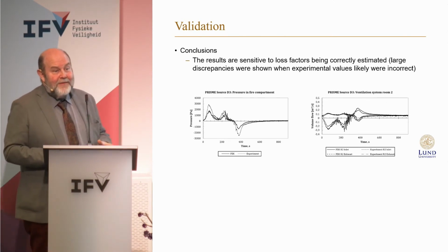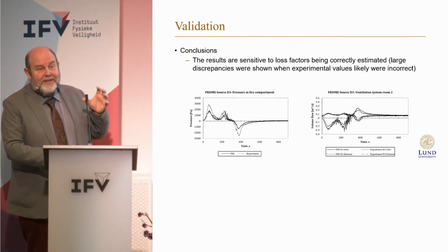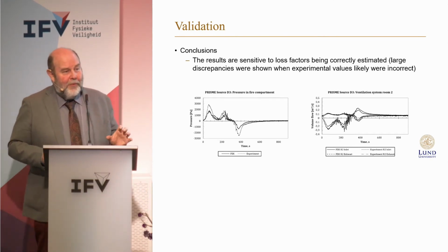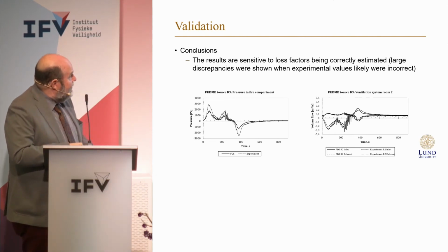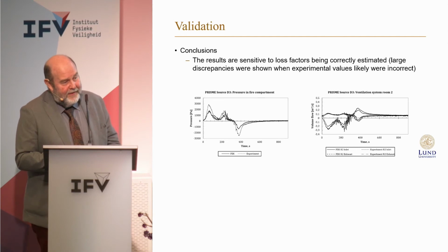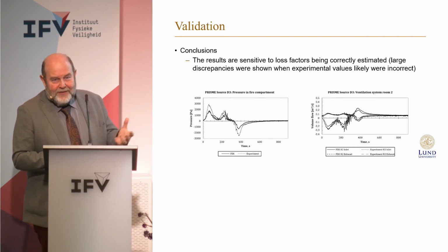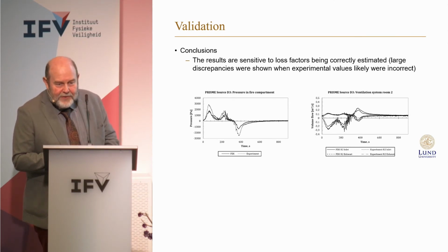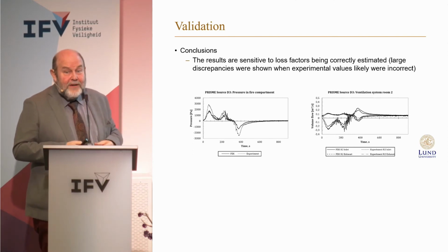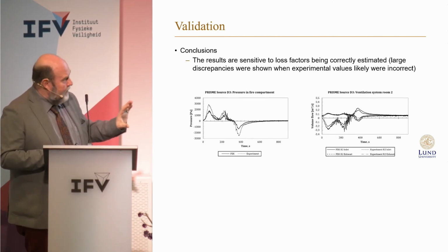In a mechanically ventilated room where there's very, very little leakage, the pressures are not as in a normal fire. That means you can get values of 1,000 Pascal or 2,000 Pascals, which of course in many cases might, if it's to the outside, break windows or something like that, but if not, you get very high pressures. And I know that yesterday there was also a session dealing with that if you had this combination of sprinklers, but this is without sprinklers.